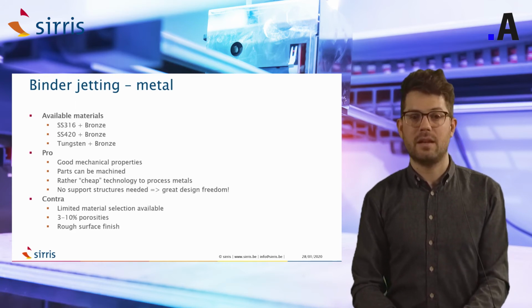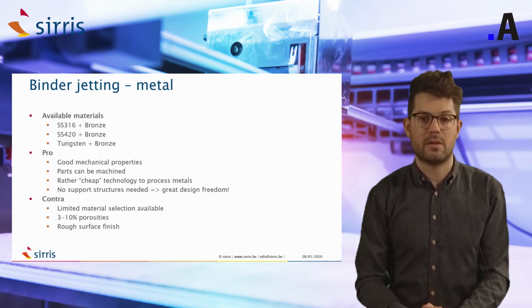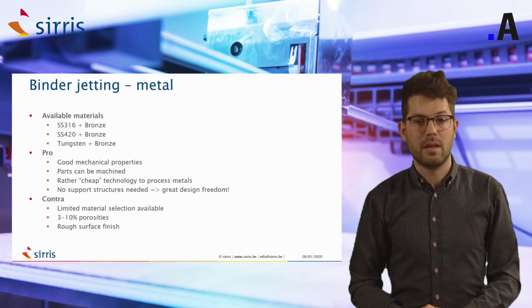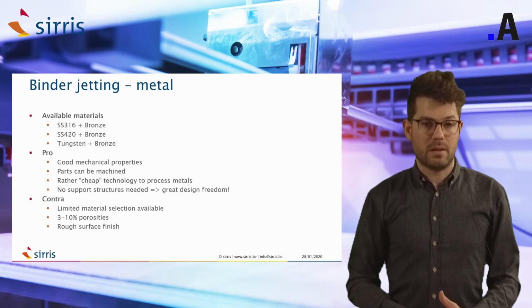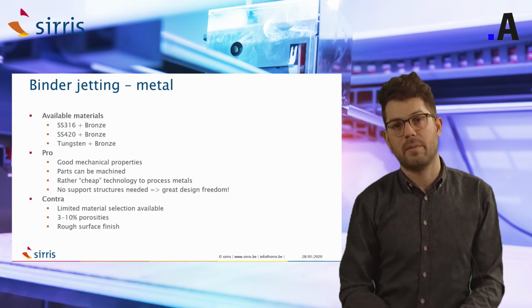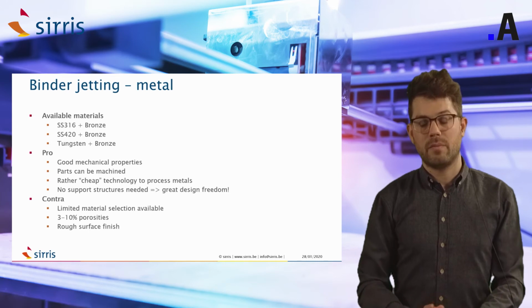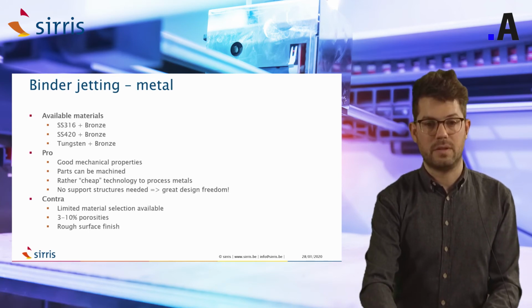But as you can see on the available materials, the materials are quite limited. There are also more porosities in those parts than in parts made by other metal technologies, and we have a very rough surface finish.